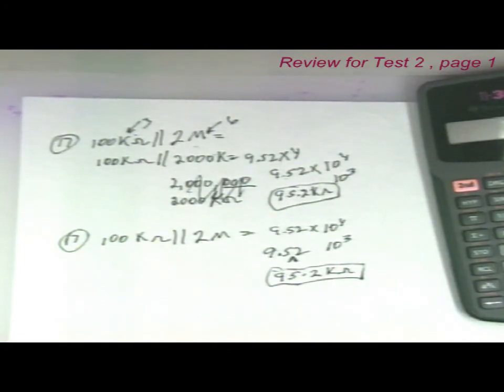If you want to measure a load voltage with a DVM, and that's a digital voltmeter, connect the meter in parallel. Now, don't you remember how you measured all those voltages in those labs? The voltages across the resistor. You're going to be in parallel with your meter, aren't you? So using the DVM, which is a digital voltmeter, you're going to be in parallel across the resistor. And what about a current meter? A current meter will go in series, won't it?